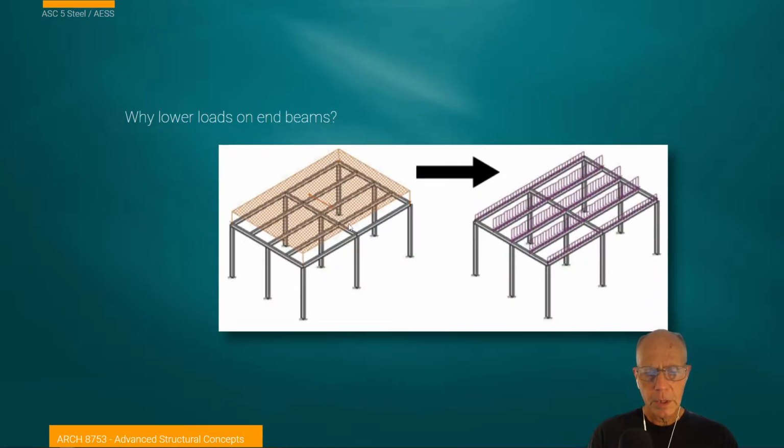So keep in mind that idea of tributary area, this idea of special conditions. The end beams now, because of that concept of tributary area, the end beams do not need to be as large because they're only carrying half of the weight that the interior beams would carry.